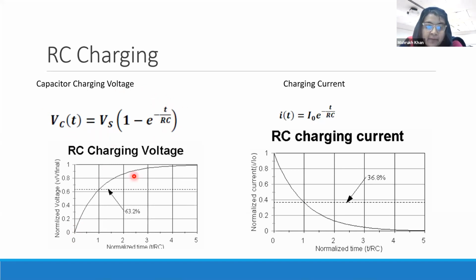So it means that, let's say you are recording time and 10 seconds pass. You can just replace T with 10 seconds here, and multiply by your source voltage. The voltage that you calculate from here should be equal to the voltage across the capacitor. Similarly, as the voltage increases, the current decreases. As soon as the voltage approaches the input voltage, there will be no current flowing, right? So that's why it's acting as an open circuit.